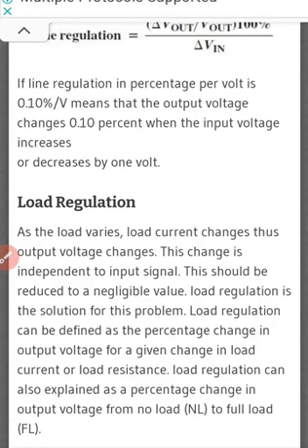So in most cases the load is connected through a resistance. As the load varies, the voltage drop across the resistance varies and the load current changes, thus the output voltage also changes. As there is a voltage drop, the current changes, and the current leads to a change in output voltage.